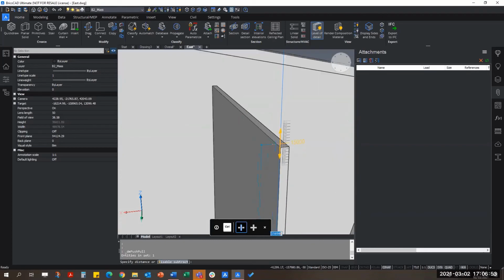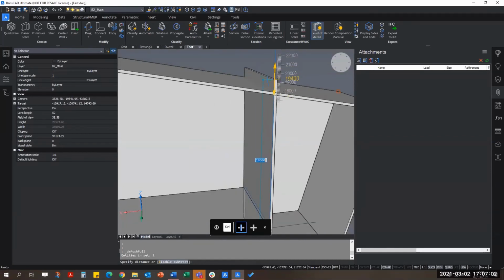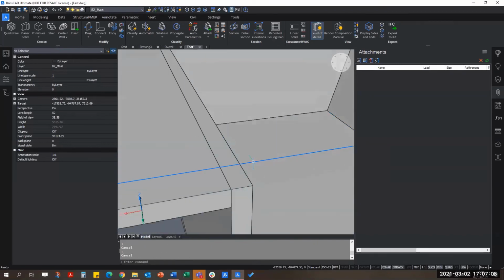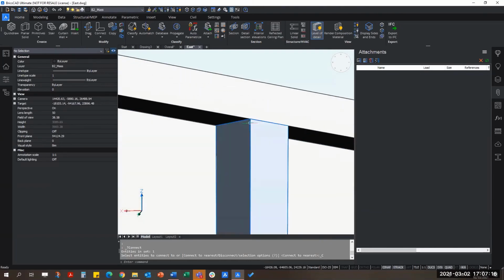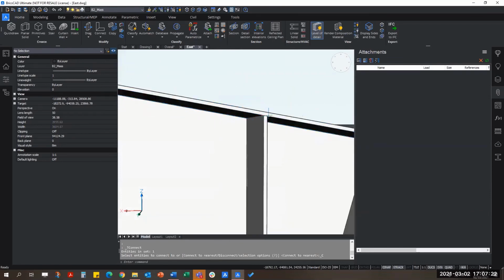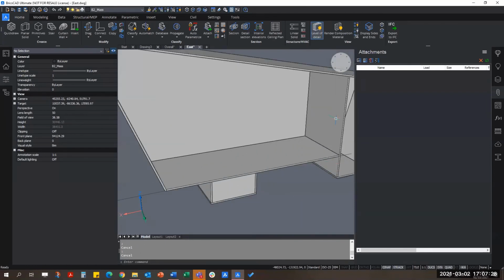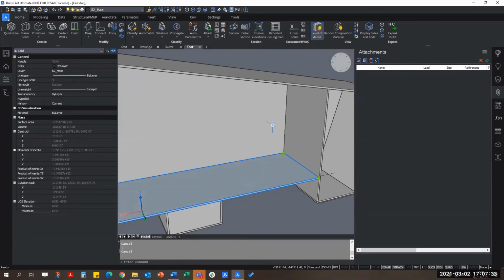However, this push-pull means that I wouldn't be able to nicely flush against this slanted roof over here, as you can see. I mean, I could either protrude it and slice it, which is quite time-consuming. So again, I'll use the connect with nearest because it logically makes sense, and it gives me the slanted portion here, and it's nicely attached to the underside of this roof.